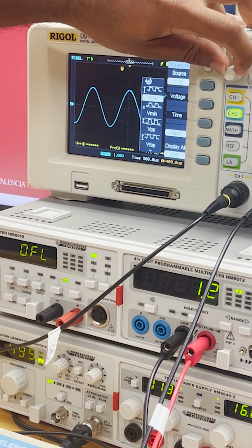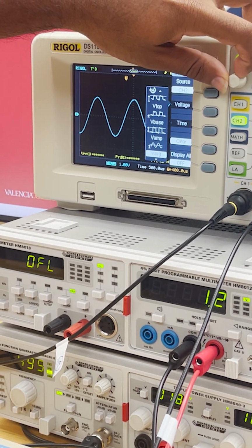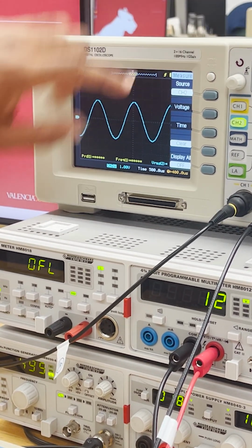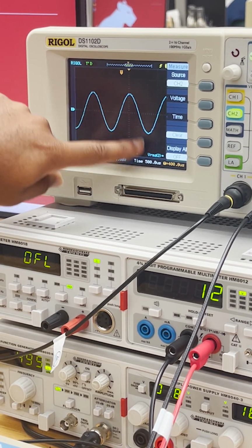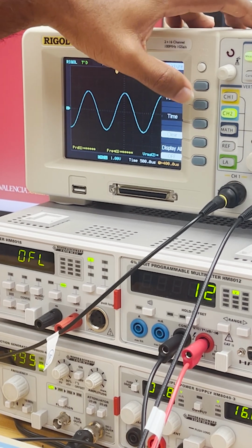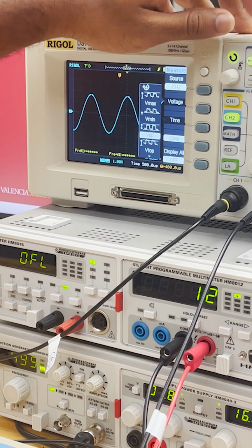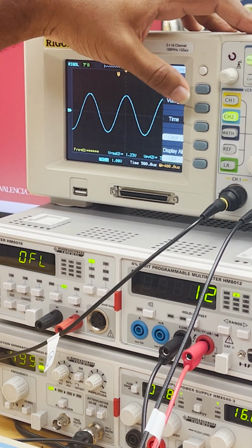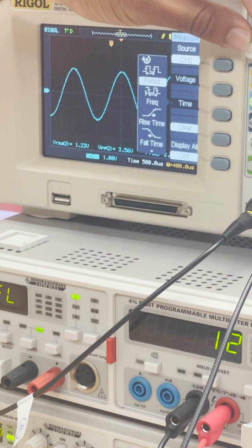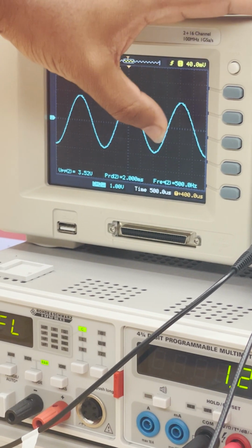Come back to our voltage again. We're going to look for our VRMS one more time. Bring that up. And as you can see, the colors change. So for our graph, it coordinates to blue. So these yellow ones are for our other measurements for channel 1. We're going to go back to our voltage again. We're going to pull up our V peak to peak. We're going to go to our time, we're going to pull up our period, we're also going to pull up our frequency for channel 2. And then we're going to remove the label again.